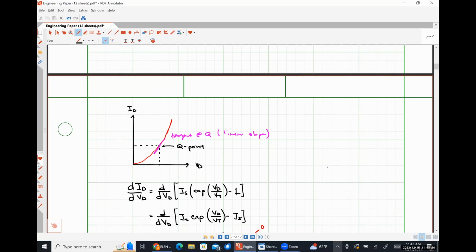So we have this exponential relationship between current and voltage for our diode, right? So the steeper that we get, or the further along the forward bias curve we get, the resistance is going to be larger or smaller. So if I over V is large, V over I is small, which means the resistance is small, right?